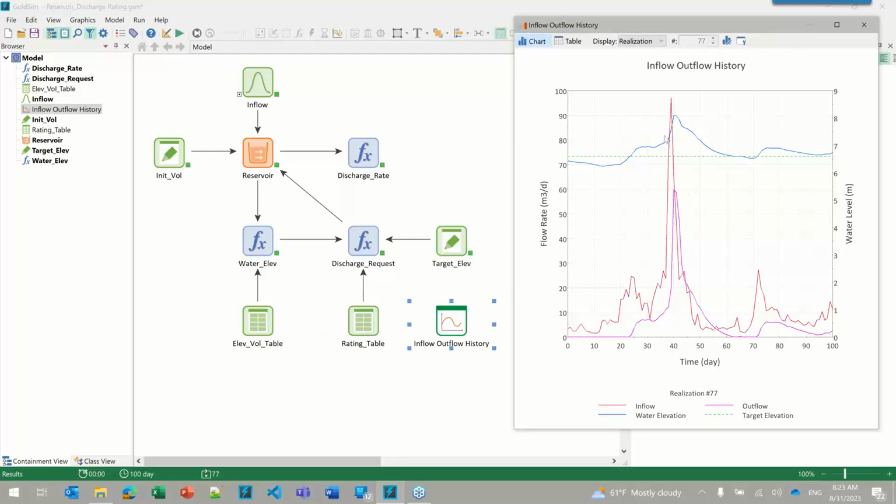And as the water level increases above about 0.5 meters, or I think it was 1 meter, once it's above 1 meter above the target, when the depth is greater than a meter, then the flows greatly increase right here. And so this is an effective way to simulate a more complicated outflow facility there. And then you can see it's dropped below, at, and below, so the flows are zero, and then back up again. So this is useful, definitely something that could be used in many models.